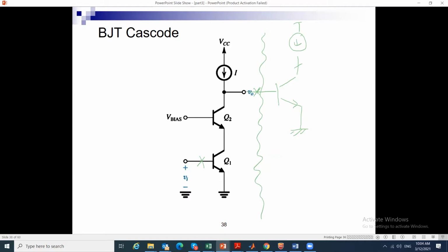We look outside my structure. Anything that loads my circuit, the derivation is assuming that this is ideal, okay, meaning R infinity. So if we tell you that this has any resistance, then you are going to lump it together with the R load that the amplifier up to point Vo will see outside its own transistors.